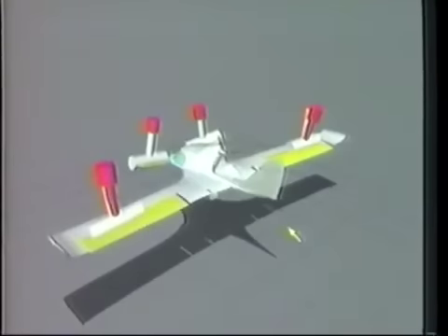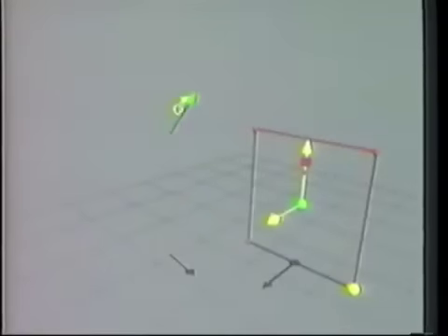Our task is to construct a user-controllable yoke that provides simultaneous control of multiple joints with a 3D interface that is both realistic and understandable. This is a good example of the utility of breaking down the distinction between application objects and widgets. Our widget toolkit is used to define the behavioral scaffolding of the yoke, which is an application object. We begin with a ray to control the rotation of the ailerons. In order to constrain the ray's rotation to one axis, we link it to the coordinate system of a plane widget.